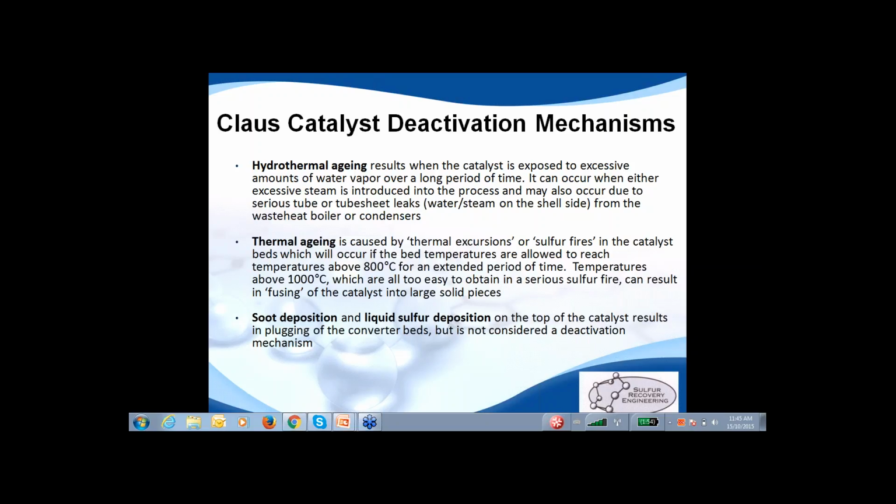We will monitor the burn stoichiometry of the fuel gas, and the goal is to achieve a burn that is just ever so slightly substoichiometric, such that we are not going to be generating soot and such that we are not going to be introducing an excessive amount of oxygen into our process, such that we can minimize the risks associated with both sulfur fires with excessive oxygen and also soot formation if we are operating too deficient.